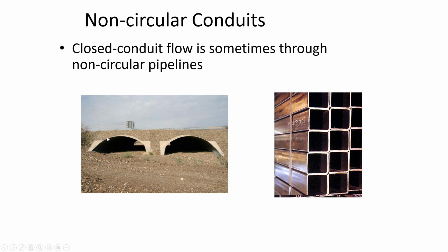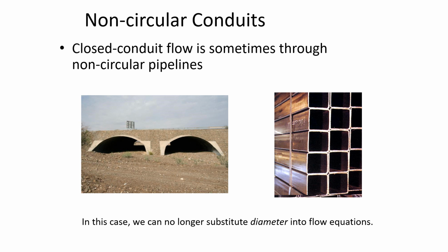They have this road with really big, you can't tell from the photo because there's nothing for perspective, but it's probably about 12 feet from the bottom to the top of that pipe. So it's non-circular. How would the friction loss formulas apply to a non-circular conduit? Well, we have to have something else besides diameter as the size parameter.